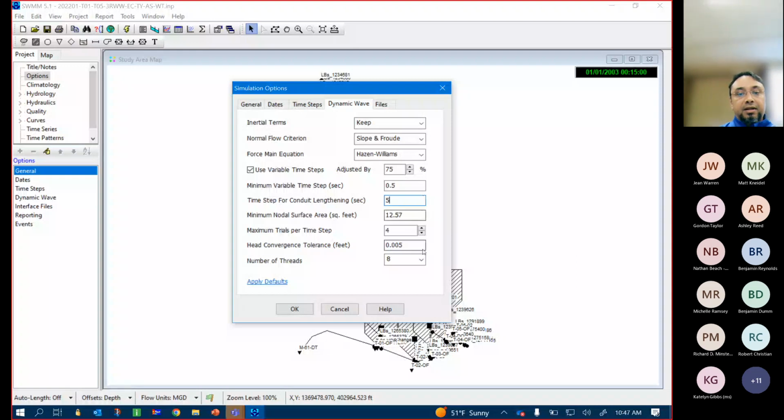so that it can converge quickly on a solution, but it's going to be working with a 5-second time step there. These are some of the parameters that help control how many iterations the model is going to be making before it converges onto a solution. These are numbers that have been optimized for Alcosan. If you play around with this, it is surely going to be impacting the runtimes. Well, for the submodels, it's not a big deal, but for the Alcosan system-wide model, these are important parameters. Recommendation would be not to mess with them.